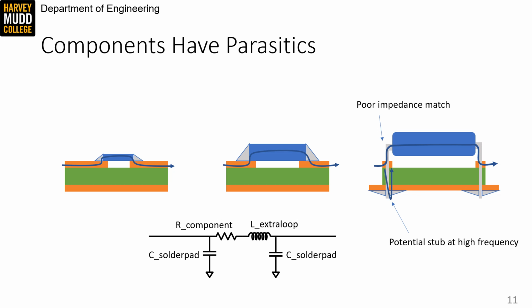And also, by the way, this process of reflecting off of a short piece of transmission line is referred to as a stub. Finally, through-hole components are simply bigger, which means that you need to consider them as sort of distributed elements at lower frequencies. So don't use through-hole components for RF designs.